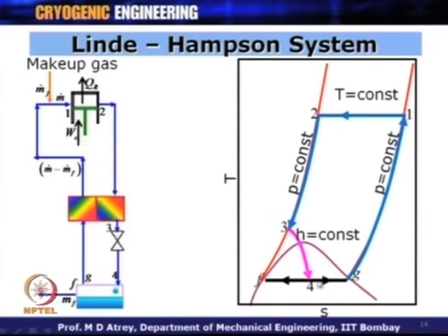All right. And 4 to G is a place where we get vapor or gas at this point, and the liquid is collected depending on where the point 4 is. Depending on where point 4 is, the amount of liquid will be decided, the amount of gas which has got converted to liquid will be decided, and this is what we will calculate now. This should be very, very clear to all of you: how to draw the TS diagram for various cycles.